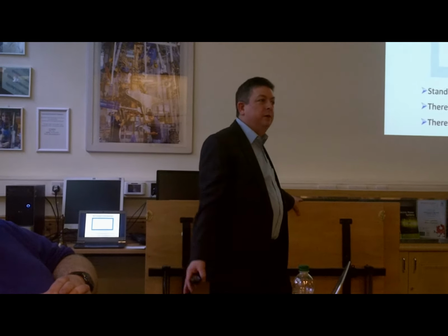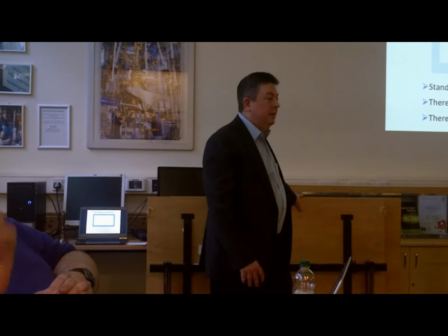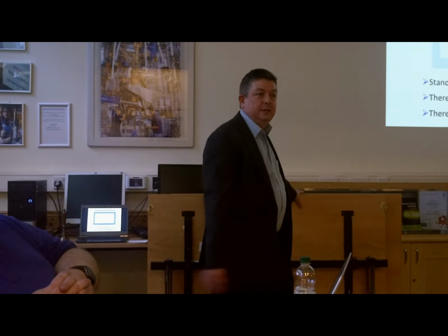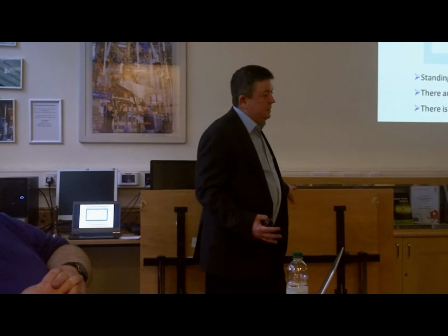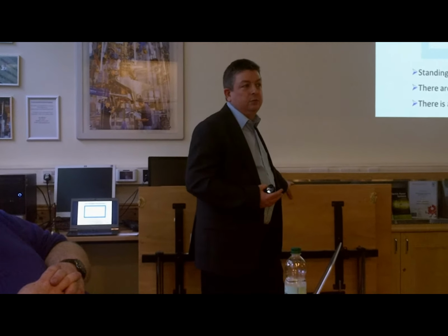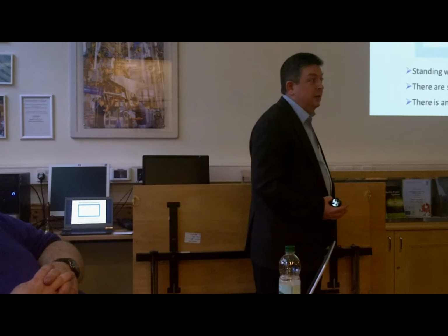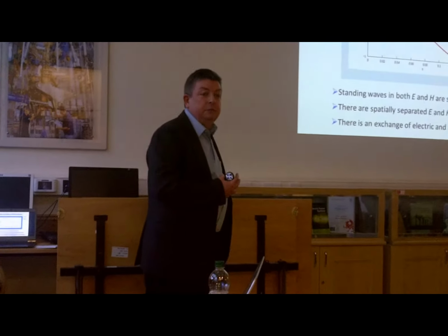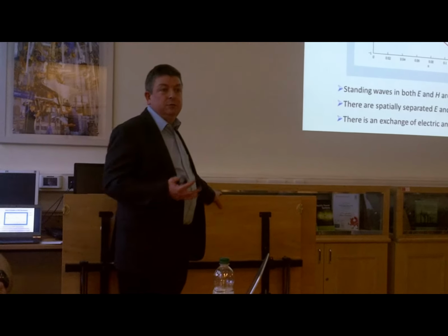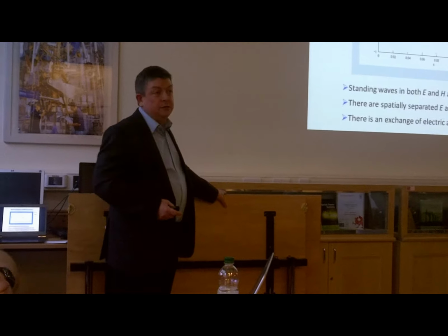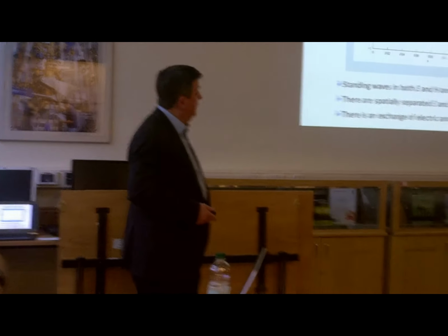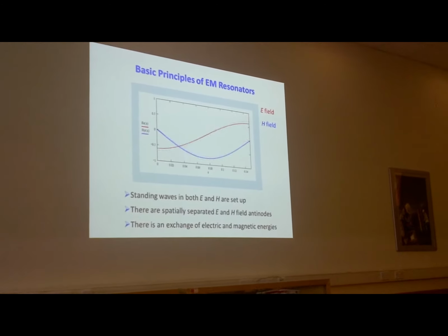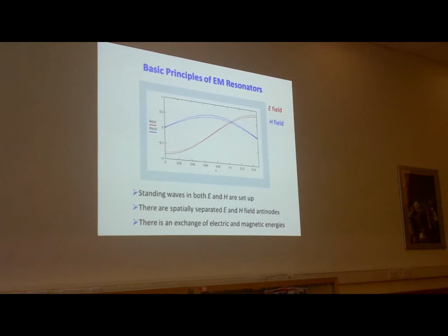So what we've got there is the classical resonance where the energy is transferring from electric to magnetic and back again, a bit like a pendulum, going from kinetic to potential to kinetic. And of course, if you introduce dissipation in that system, then that energy decays away, and we end up with the concept of Q factor. So if we can measure the resonant frequency of this system, and also measure the Q factor, then we can tell about the loss mechanism and also the stored energy mechanism as a result of the interaction with this particular field.